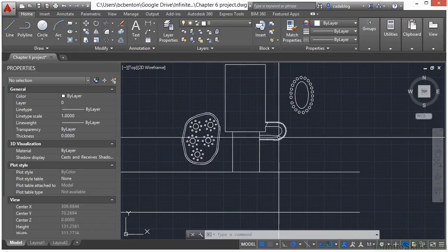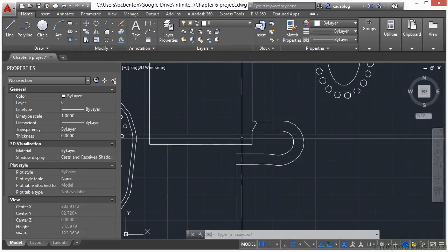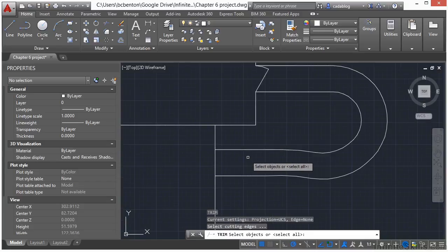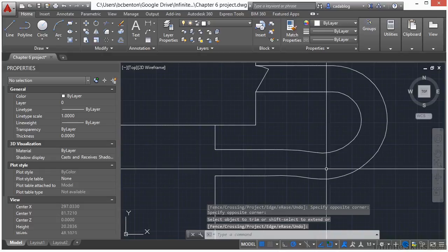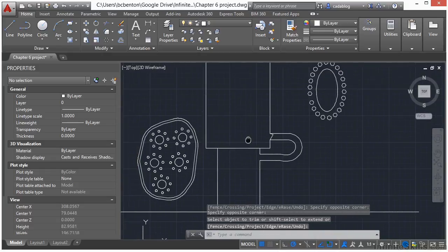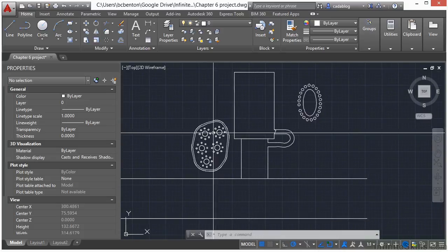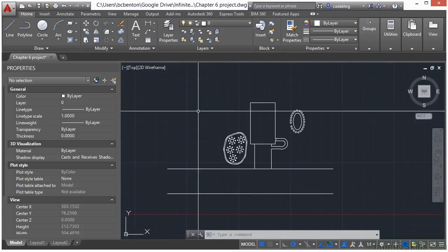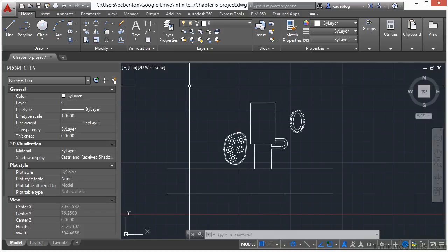We have edited our drawing. We've trimmed up the doorway here to come into our building. And we can even trim up this right here. Use the trim command, select these 2 lines and click that. So now this is one concrete pad. We cleaned up our pond with our stones and we cleaned up our planting area. So now you've seen how to create a drawing, and now we've seen how to go back and edit that drawing to make improvements to it.